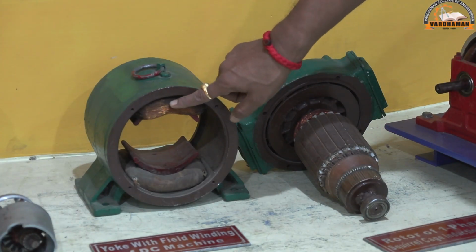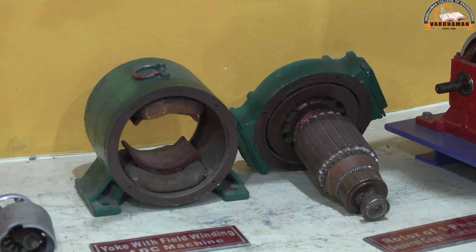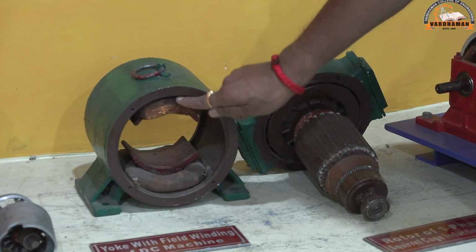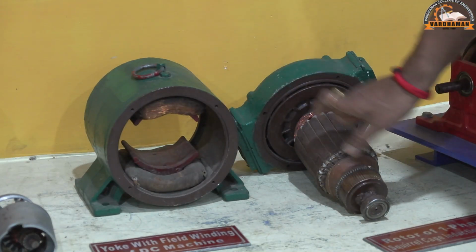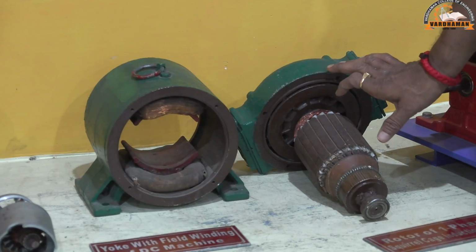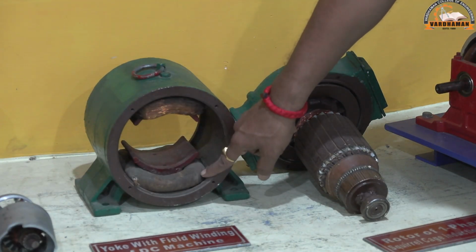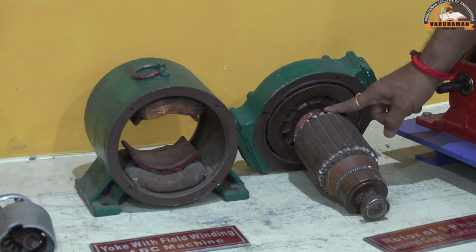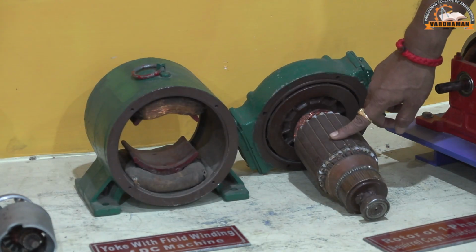So you have a connection between F1 and A1, F2 and A2, and a common power supply is given. The same current is going to flow through the magnetic field coil as well as the armature conductor, since we have a connection between the magnetic field coil and armature. So the same current will flow, and the purpose is fulfilled in the magnetic field coil, and the same current will flow through the armature conductor, which is going to create the flux by the current carrying conductor.